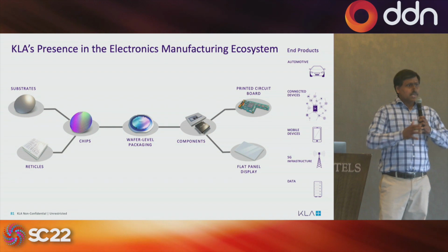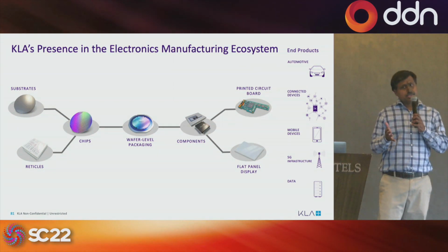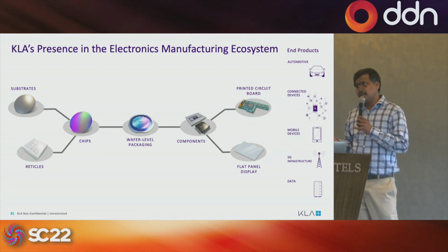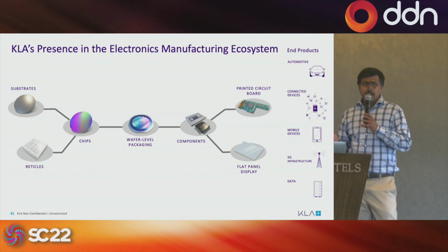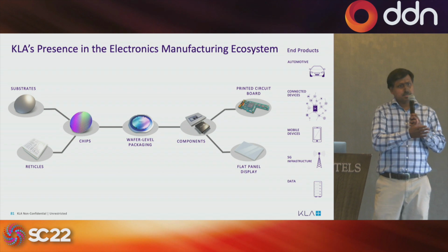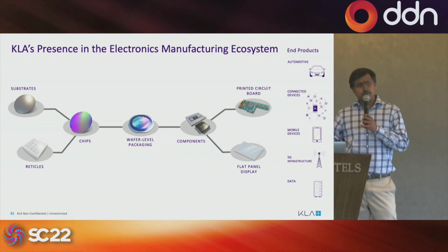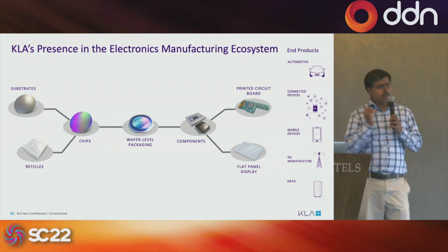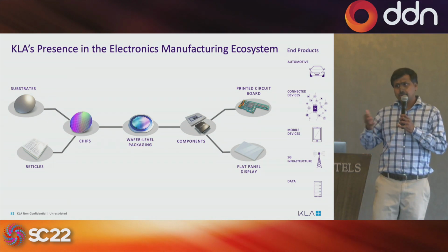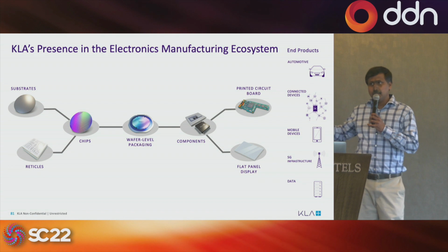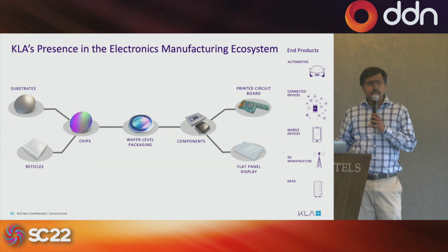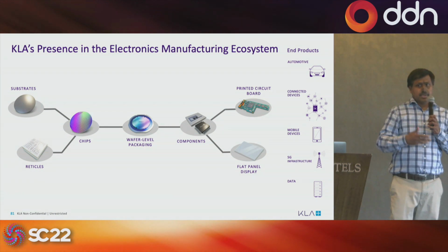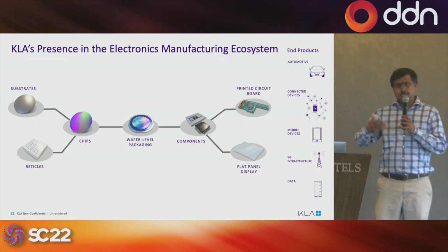So once they make the chip, they can put it through electrical testing and functional testing, and determine whether the chip is working or not. But in most cases, these hundreds of process steps take about 5 to 6 months. So driving blindly for all that period without knowing what the final outcome is not good for them. So what they want is inline monitoring of their process steps.